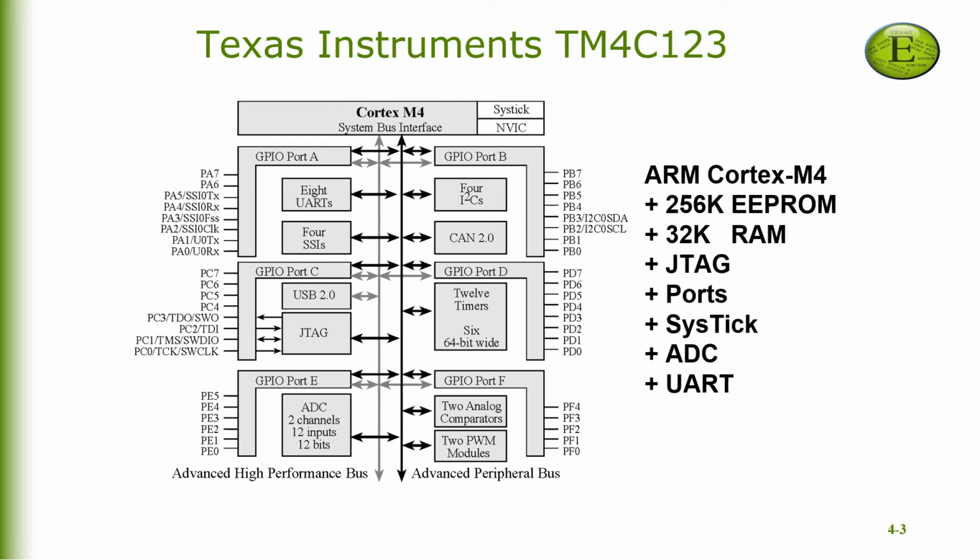Now, if you can recall, we discussed in the very first lecture that our microcontroller can have several input-output ports. So here in this case, we have port A through port F, so 6 different input-output ports. And there can be at most 8 pins on any port. Some of them may have less than 8 pins, like in case of port F.